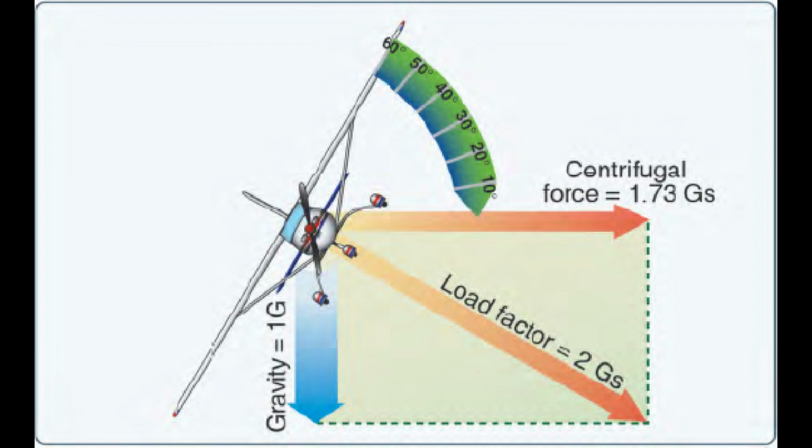Load factors are important for 2 reasons. 1. It is possible for a pilot to impose a dangerous overload on the aircraft structures. 2. An increased load factor increases the stalling speed and makes stalls possible at seemingly safe flight speeds.